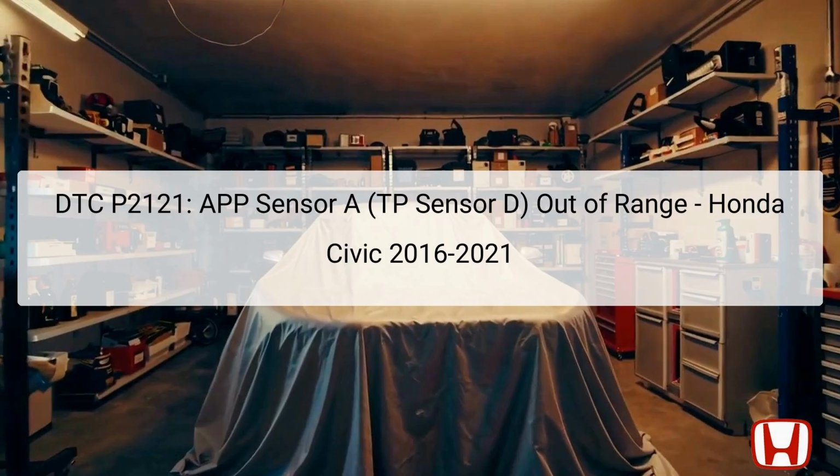Proper operation of the APP sensor is crucial for vehicle responsiveness, fuel efficiency, and safety. When this error code is present, it signifies either a malfunction within the sensor itself, an issue with the wiring leading to the sensor, or a potential problem with the ECM interpreting the data. Hence, troubleshooting the P2121 code is essential to ensure that the vehicle performs efficiently and safely.